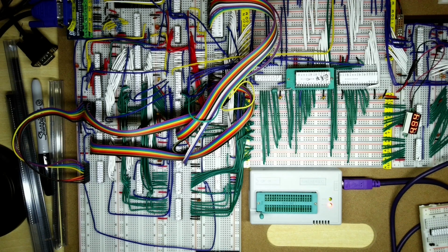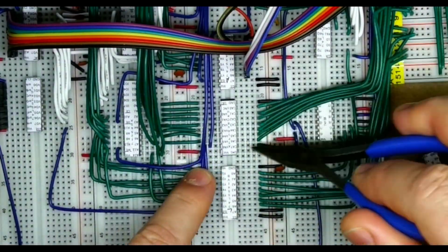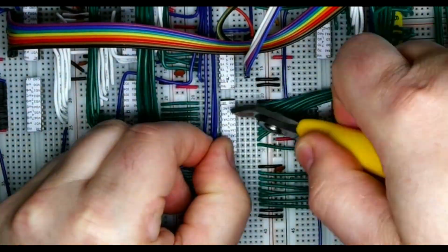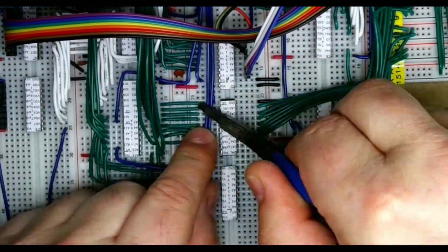So what I'm going to do is I'll just go and speed up that video as I make all the changes, and then I'll commentate over it. And so when we come back, hopefully what we've done is put in the multiplexers, and then we'll fire it up to see whether or not we can switch between the character mode and the high-res graphics mode. So first of all, take out the old buffer chip and put in the new PLD, just checking the right-hand side address lines match up okay, and just putting in the output enable.